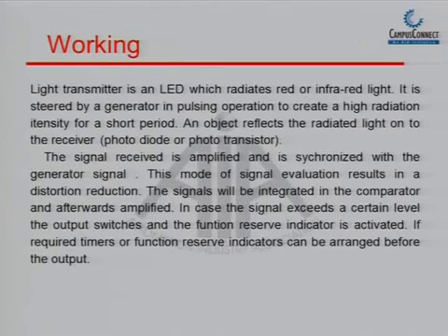If we talk about the working principle of a photoelectric sensor, it consists of a transmitter and a receiver, that is an LED. The light goes out of the sensor, gets reflected back from the target, and based on the light that has been received, we amplify. There is an amplifier inside the sensor, it amplifies the light and then calculates the intensity, and based on that we decide whether there was a target or not.